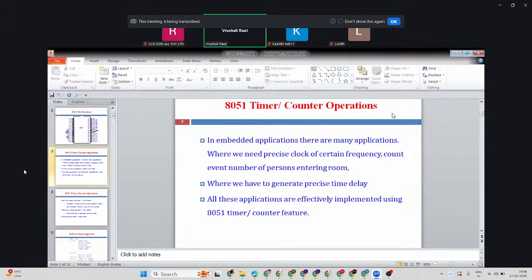Okay. Now for example, I have to measure the speed, or the rotation, of some wheel. That I can do even with the help of a counter. Okay. I can place the LED and the receptor which will receive the light of the LED, that type of sensor arrangement. And the wheel is rotating. When the wheel is rotating, wherever there is a hole in the wheel, the light will pass through. I'll be counting those pulses, and the counting will happen. So for a number of applications, this can happen.